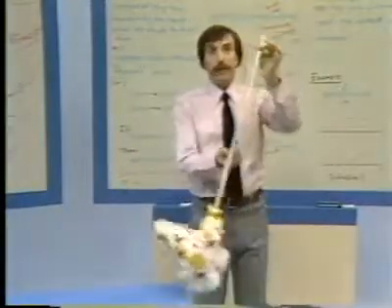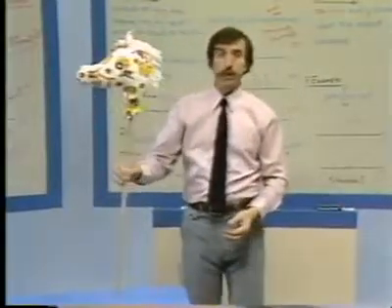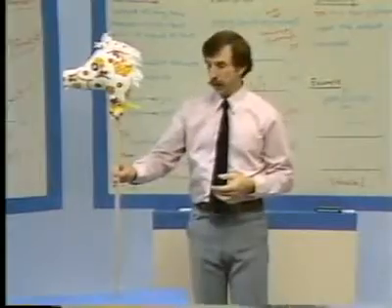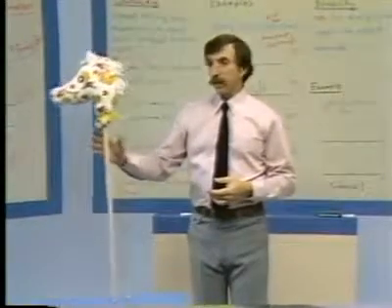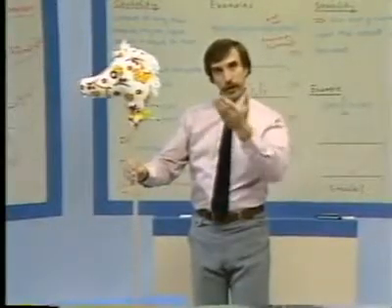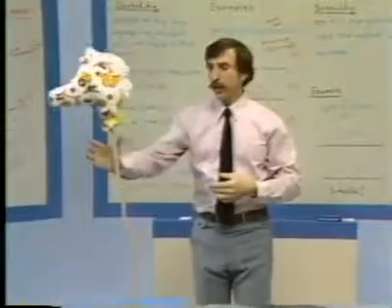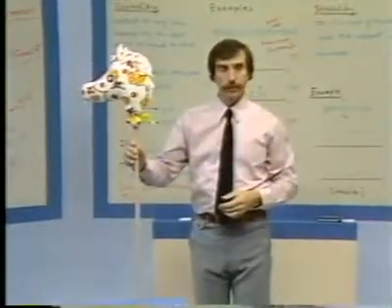Now, on the other hand, if I put the system like this, which is in fact what's referred to as an inverted pendulum, although we could conceivably get this to balance, just a slight displacement, because of the fact that the pendulum is inverted, a slight displacement and the output becomes unbounded.